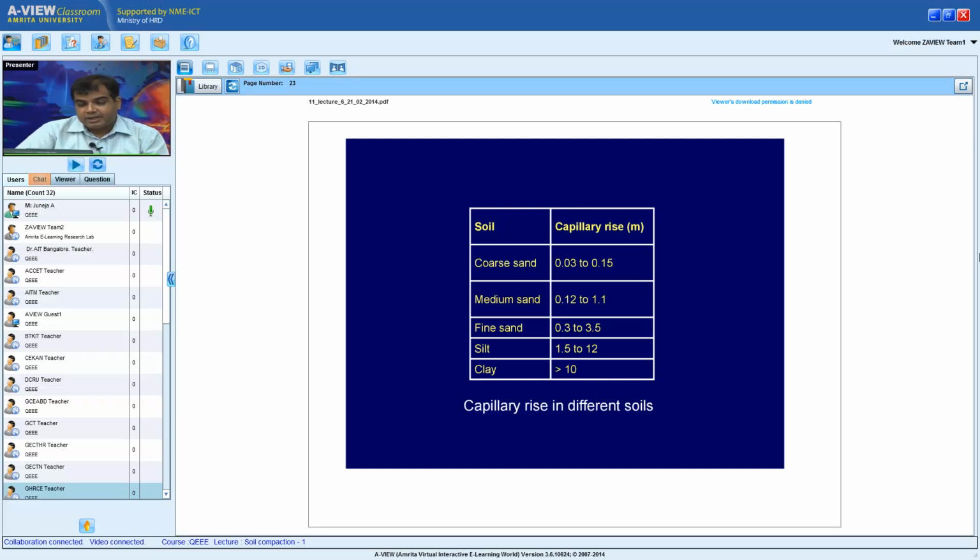There are some fine examples available in literature, wherein because of the soil capillarity in clay, on the upstream side of the earthen dam, the water starts to rise up because of capillary action, and the water level in the dam has gone down. So I think you can refer to some textbooks which have pretty nice examples.